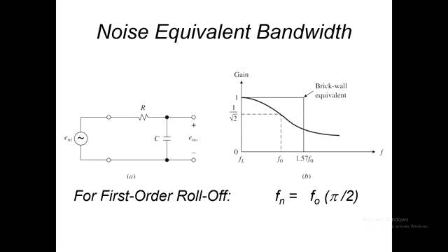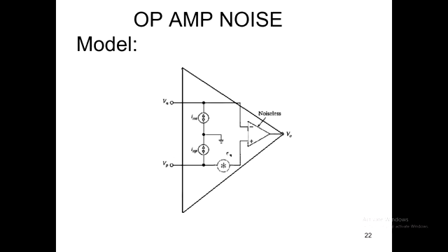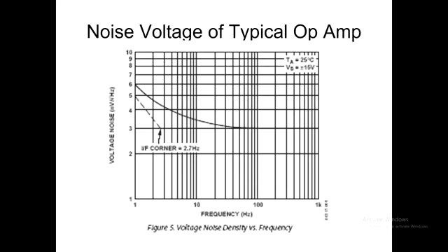And blow me down, the manufacturers provide us with that if we're good, or we have to figure it out ourselves otherwise. But if they have good op-amps that are good in that category of low-end behaviour, they will definitely advertise the corner frequency for you. The index of a good quality low noise amplifier is a low corner frequency and a low white noise floor.